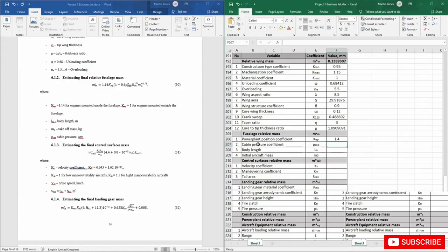So once the aircraft is over 3000 meters, then the passengers cannot breathe normally if we don't apply pressure in the cabin. So we simply apply pressure in the cabin and not oxygen as well, in order for the pressure there to be enough for life, or for the passengers not to feel uncomfortable.